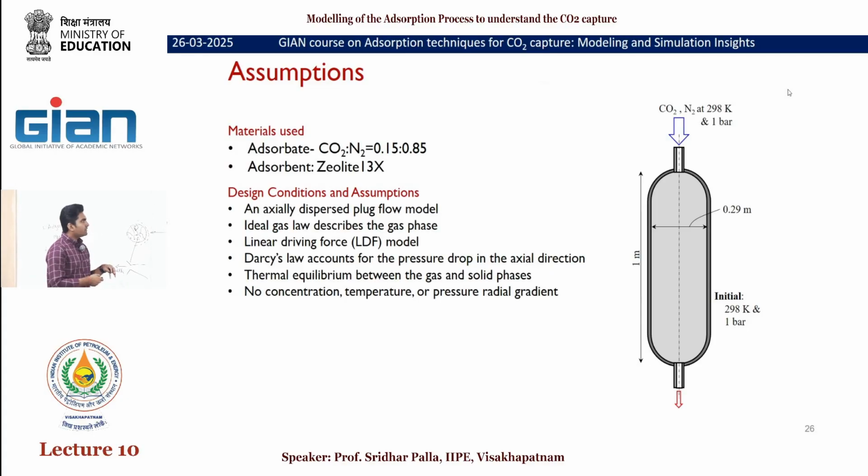And also the linear driving force model, okay, if we are not considering this assumption, then we need to incorporate all those micropore diffusional resistances, everything we need to consider. And also you can go for Darcy's law or Ergun's law or Navier-Stokes, okay, to get the pressure difference in the bed. Then thermal equilibria.